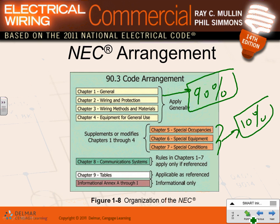These other chapters are specialty, where you can spend probably 10% of your time. They cover special equipment, special occupancies, hazardous locations, as well as special conditions. And then if you're doing telecommunication, can you guys see that? That's where you're going to have a whole chapter for yourself. And all the calculations and tables are in chapter 9. Everybody can see that? Rules in chapters 1 through 7 apply only if referenced from this chapter. It's almost not part of the whole book. Tables are applicable as referenced only, and annexes are FYI only. Annexes are FYI only. Everybody knows what FYI only means in terms of enforcement? Can't emphasize this enough. Can I have a thumbs up, Chad? We fully understand how the code is laid out.